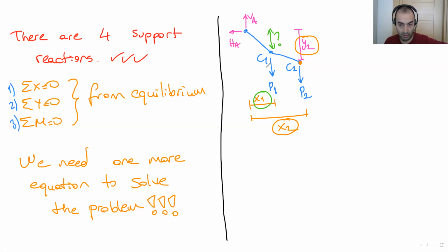Okay, so if I know everything regarding the C2, can I write this equation like total M_C2 equals 0? Yes, I can write, because what I said at the beginning, this is a cable, this is a bendable material, bendable stuff. So they don't carry any bending moments.